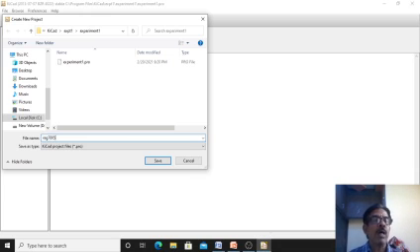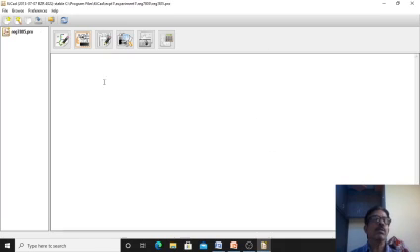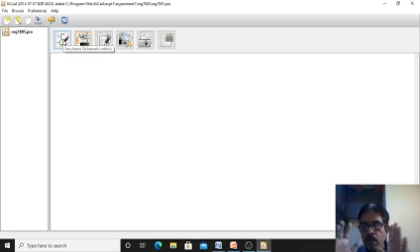Any name you can give. I have given REG 7805. Then click on Save, then click on Yes. Here 7805.pro, your project is saved. .pro will come automatically. Now I require an editor for designing the circuit diagram, so click on this icon. This is called Eeschema, or the schematic editor.